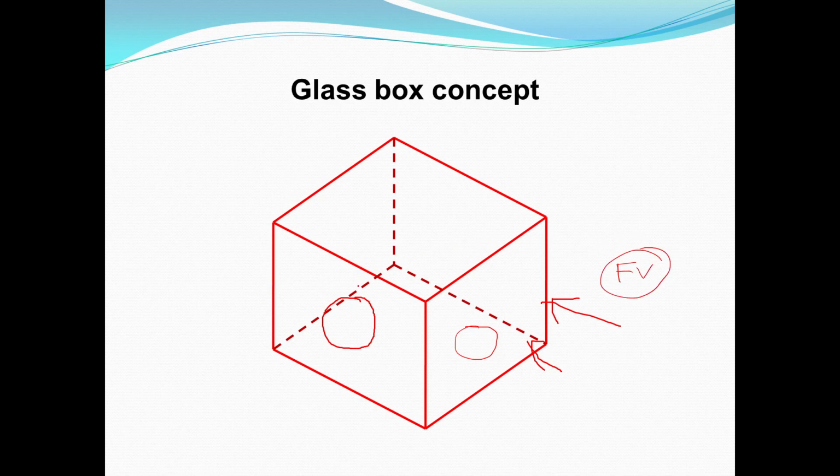And if you are looking from the top, you will get the projection on this horizontal plane. It's the top view of the object. You can see the observer is looking from the top. This is the plane on which you get the projections of this object. So observer, plane, and this is the object.